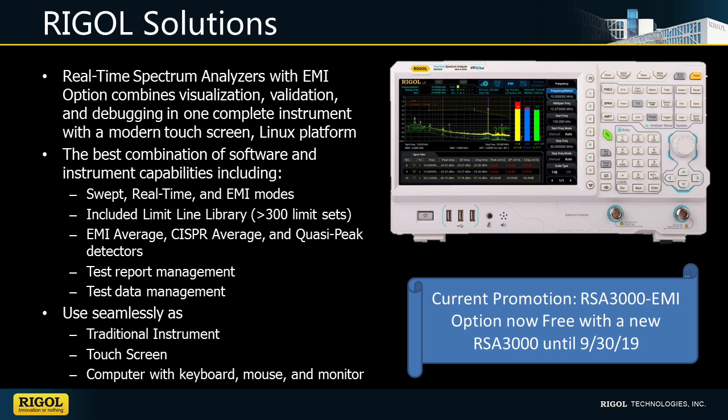So now we've looked at all of our visualization, validation, and debug tests across radiated, conducted, and immunity compliance measurements. That really shows you that we can debug everything, from simple radiated emissions using a power supply and looking at the cause and effect of a switching power supply's conducted noise, to our radiated emissions, and finally to using the full capabilities of real-time mode for the time-correlated debugging we can do with both a scope and a spectrum analyzer together.